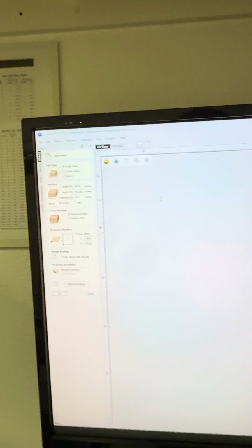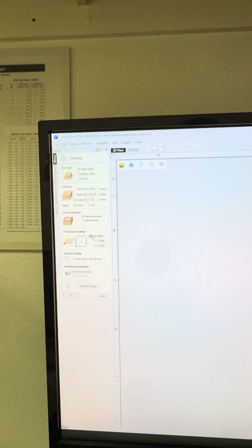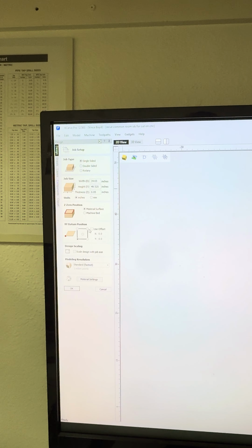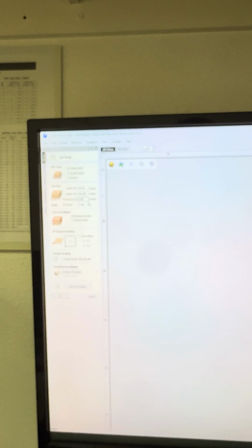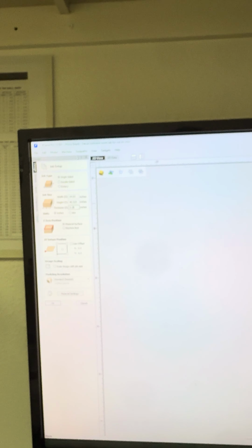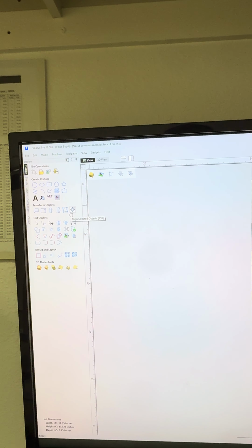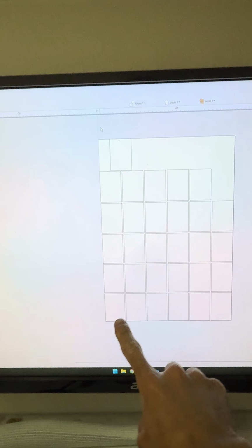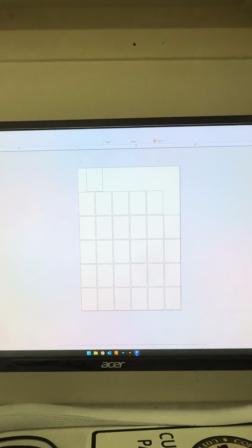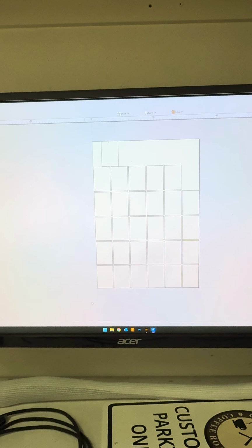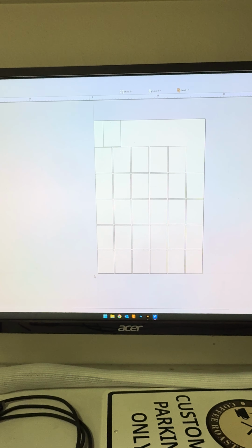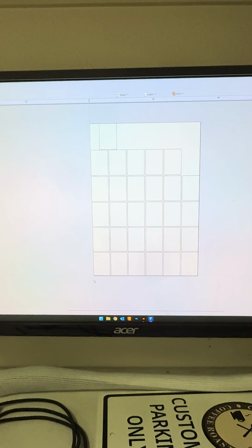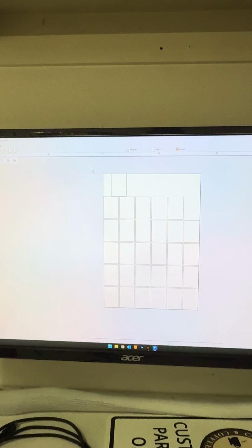First thing you're gonna do is set the thickness. Make sure there is no offset, so unclick this. Set the thickness of the material, which is 1/4 inch in my case, and press enter. Now, you can see the fine line for the X and Y. Barely can tell it, but you want that to be in the corner right there, so you can actually accurately set the XY. Next step is to highlight the images you want to cut.